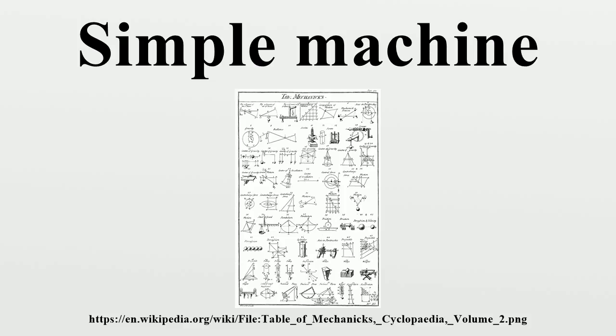However, in some machines, if the frictional forces are high enough, no amount of load force can move it backwards, even if the input force is 0. This is called a self-locking, non-reversible, or non-overhauling machine. These machines can only be set in motion by a force at the input, and when the input force is removed will remain motionless, locked by friction at whatever position they were left.